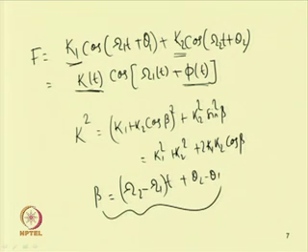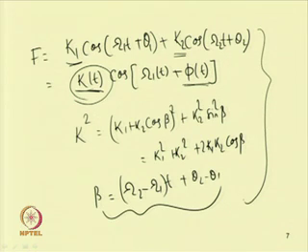So, one can add these two forces, but while adding, one can see this coefficient no longer remains constant, and we have a time varying coefficient in this case. So, for multi frequency excitation, we can add them to make a single frequency, but in this case the coefficients and the phase will be a function of time. So, we can analyze this type of situation also, in case of multi frequency excitation.